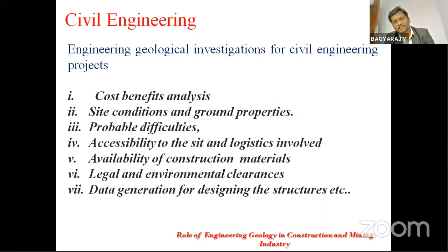So engineering geological investigation for a civil engineering project can start before the construction, and we have to assess many different aspects, which include cost benefit analysis, site conditions and ground properties, probable difficulties, accessibility to site and logistics involved, availability of construction materials, legal and environmental clearance, and data generation for designing the structures, etc.